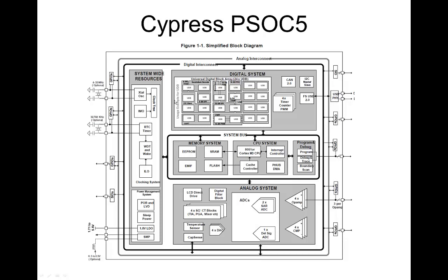But we also have reprogrammable digital fabric here, and it's more of a CPLD rather than an FPGA. Remember, a CPLD uses AND/OR planes with muxes, whereas an FPGA uses lookup tables, so it's more of a CPLD. And using this type of stuff, you can actually build things. So here they show you, okay, these 3 UDBs can be an I2C slave. If you use 2 UDBs, you can make a UART and things like that. So it's kind of interesting.